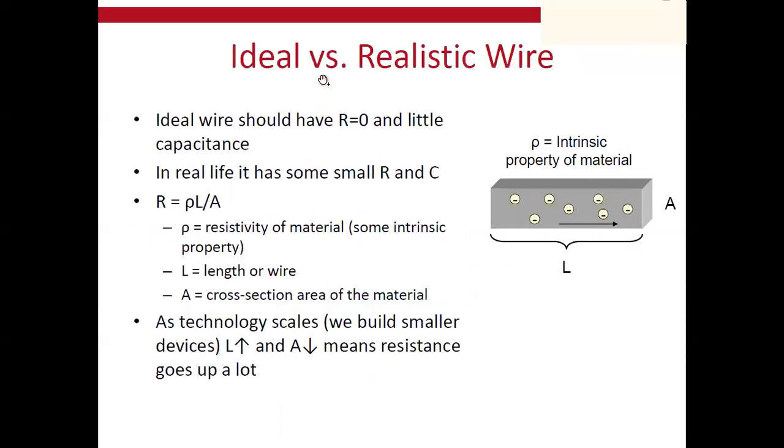other sorts of delays, which is the interconnect delay. So what is the interconnect delay? Simply, it's very basic and related to how you are considering the wiring between gates, because we have to connect gates and terminals using wires. So ideally, we consider these wires to have zero resistance, so no voltage drop, no effect. When we go from a node to a node, in circuits we even consider it one node whenever you have a wire.